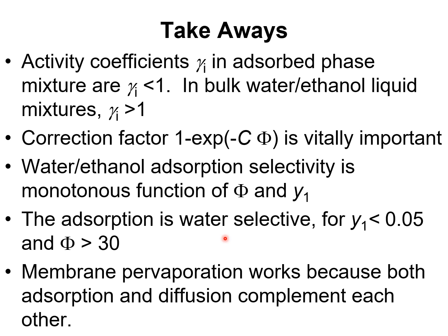The diffusion selectivity is in favor of water because of the smaller size of the water molecules with respect to ethanol, and therefore in membrane pervaporation using, say, DDR, Chabazite, LTA 4A zeolite, and ZIF8, both adsorption and diffusion complement each other.